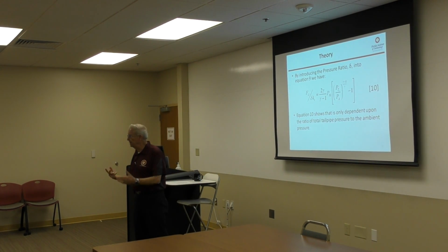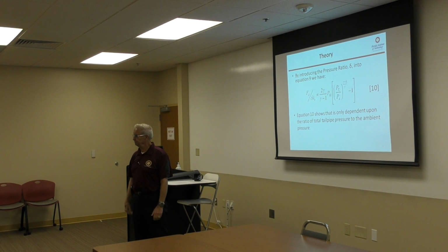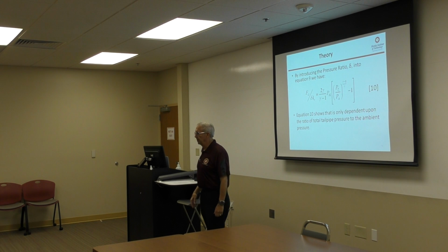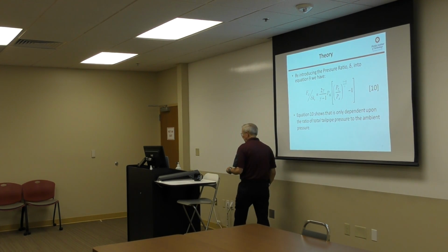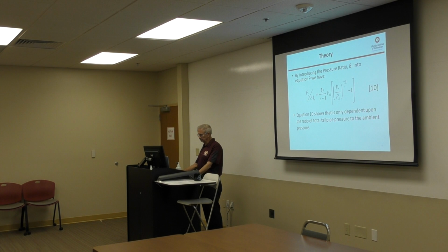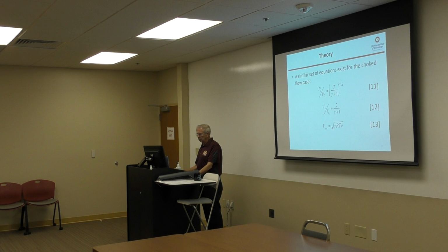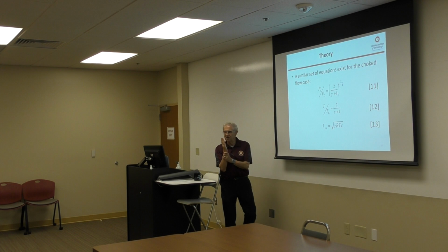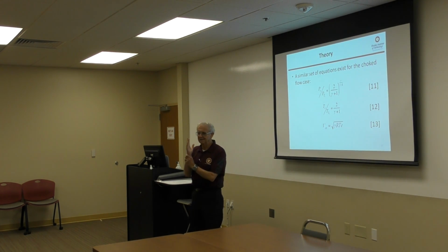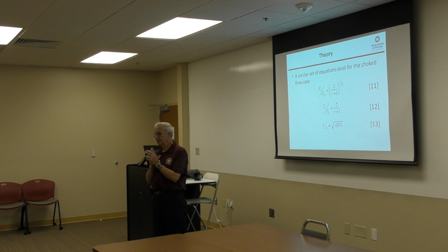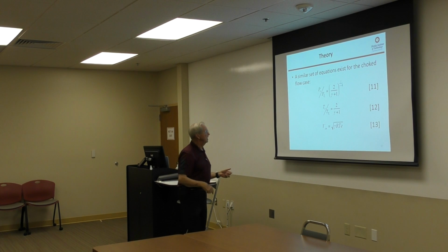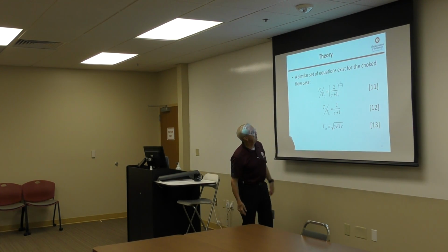but others would make the comparison since they had, they'd get that ratio since they were on board, and you could plot that up and then get the thrust of that the engine's producing, at least the gross thrust. Well, a similar set of equations, once you get that standing shock wave in the nozzle, now we've got the choke case, and so we have a set of equations for it.